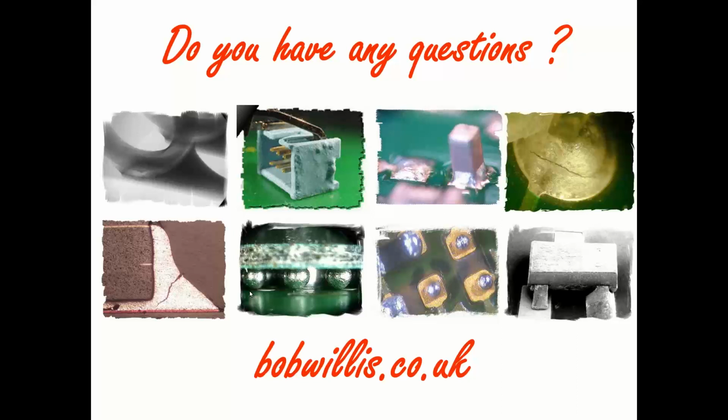So what has happened to me when I've seen this and investigated it, you can use X-ray and you can see the cracks in the solder joint, and obviously you can do the microsections afterwards, but normally you'd be able to detect it with a high-end X-ray machine today.